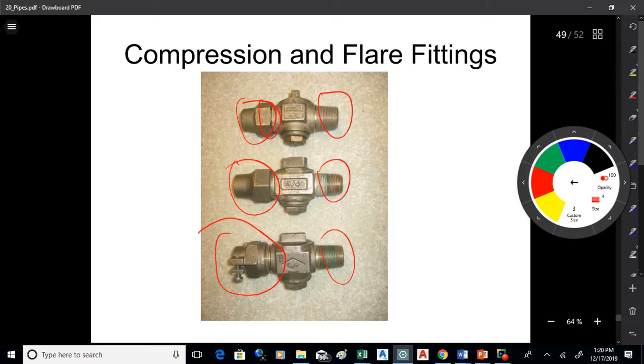Here's a little bit less strong of a connection called a compression fitting. That's a similar kind of deal here. You put that on, you then push the service pipe into this valve here, and then you tighten this up. And what that does is pushes on a thick rubber gasket and makes that gasket kind of bulge out, and that actually holds the pipe in there. So there's some fittings on service lines.